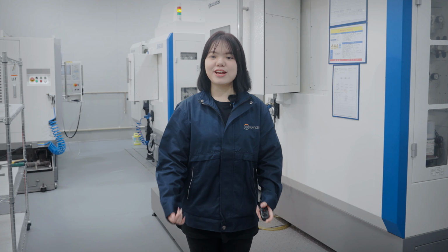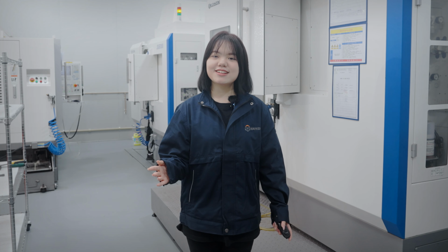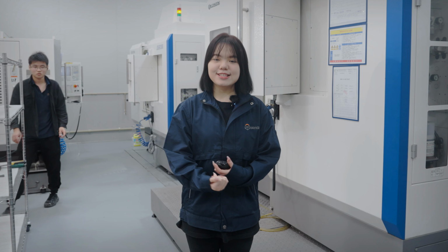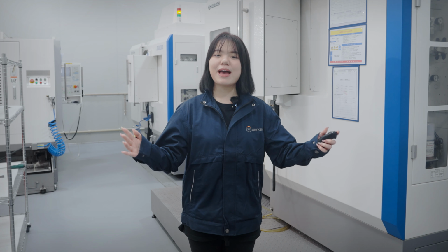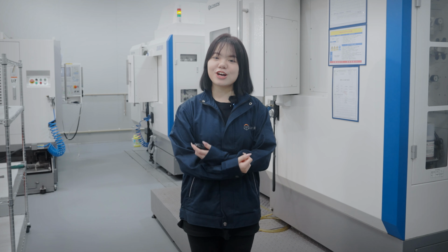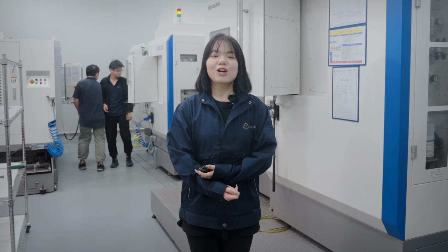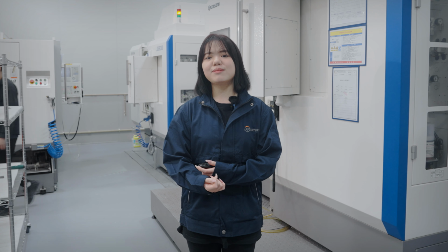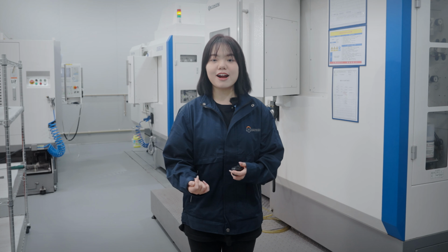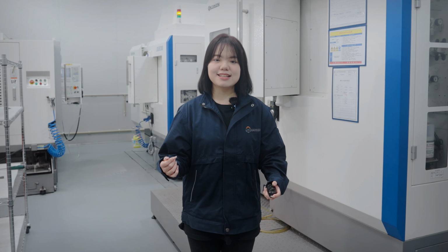Wayken once encountered a situation. For the same part in the same location, the customer provided 2 different tolerance requirements, 0.05 and 0.02. While the difference may seem small, it actually had a huge impact on the machining costs. The change in tolerance nearly doubled the scrap rate, causing the price of the small part to increase by a full 100%. This seemingly minor difference resulted in a significant increase in labor hours and machining difficulty. But when the customer finally received the part and put it to use, the feedback was that the 0.05 tolerance was more than enough to meet their needs.